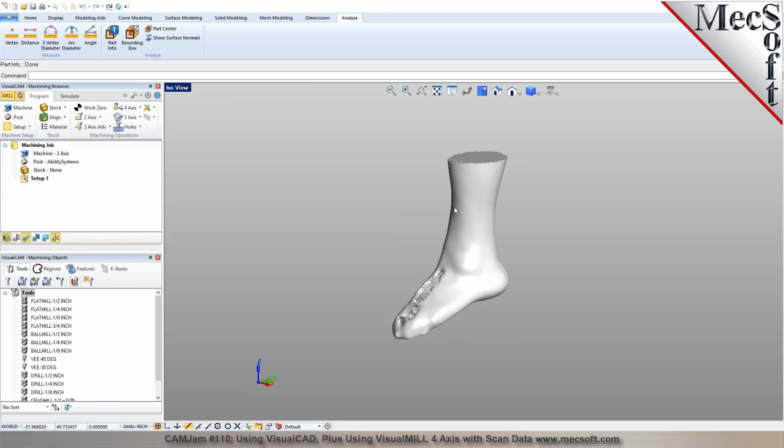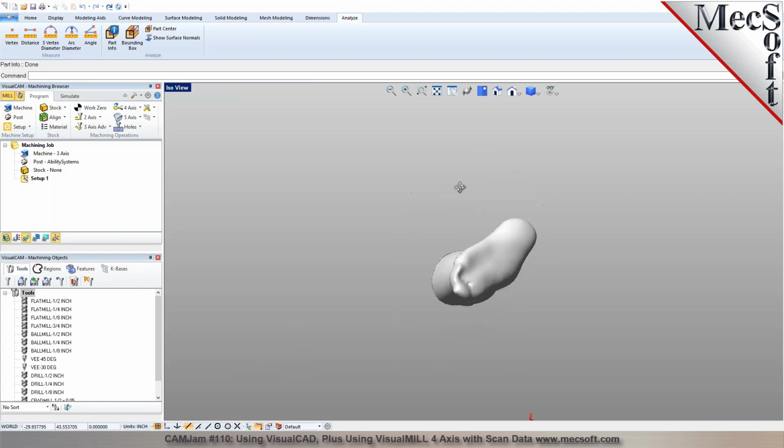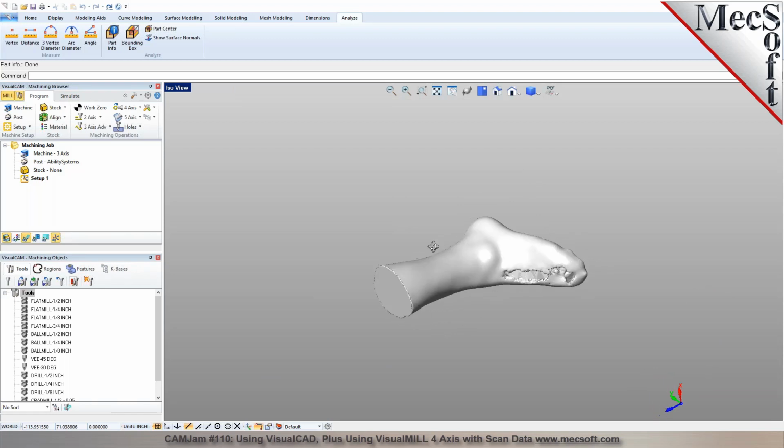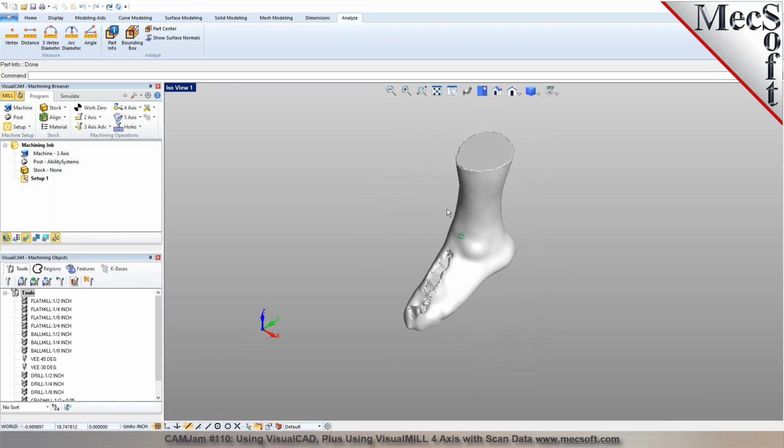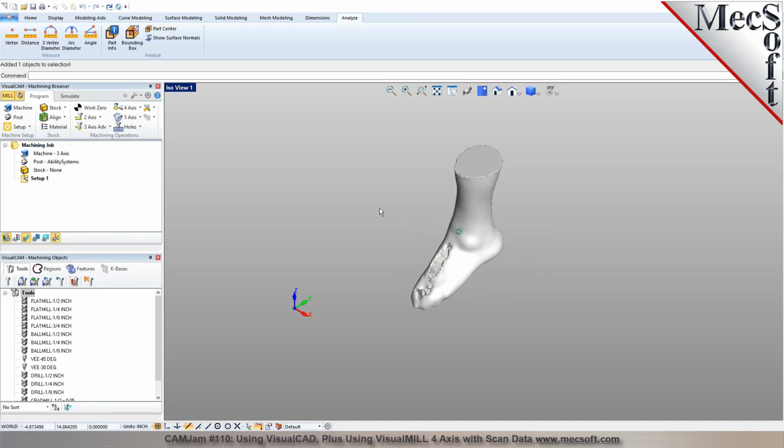Now, to mill this part on your CNC router, you probably have to place it on a side this way right here, and your router can hold this part. Your chuck could be on one of the ends, and you can machine this part. So you need to orient it along the axis of rotation. Is your rotational axis parallel to X or Y on your CNC equipment? I think it's on the Y. On the Y? Okay, X. Okay, not a problem. So we can rotate the part.